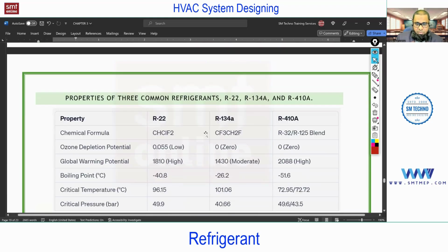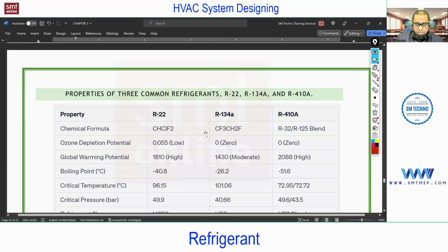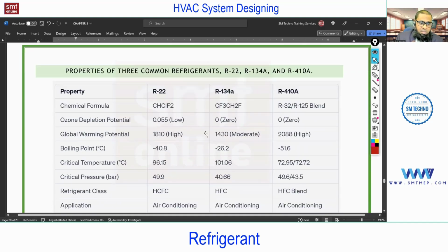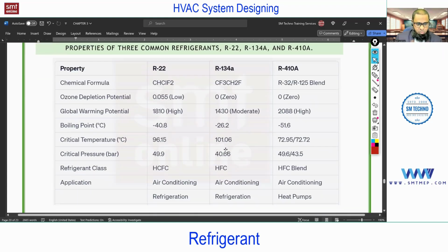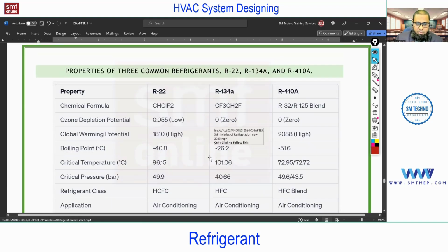We may ask in interview, so go through it once, especially for these 3 refrigerants. I have given this GWP and ODP for different conditions. Just go through once; it may be asked in interview. Actually, these details are required for the service side, because in service you must know the pressure rating and all conditions for the different refrigerants.